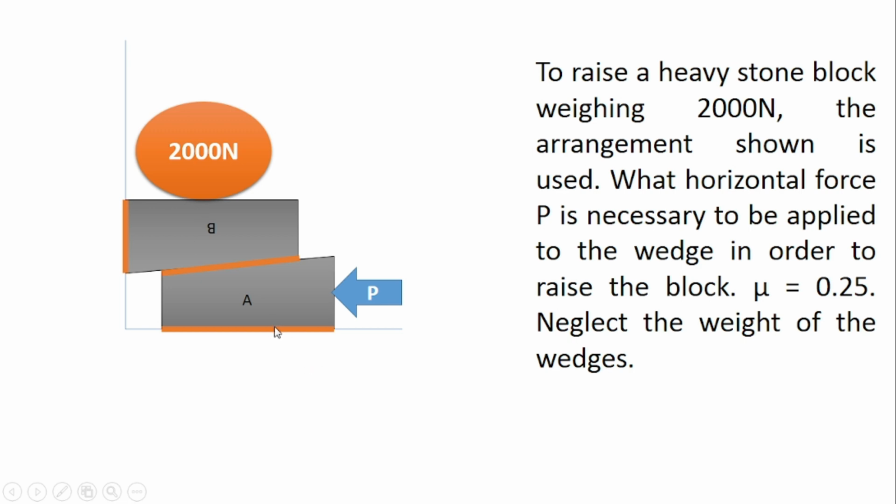So we have to draw the FBD for the 3 surfaces. While drawing the FBD, first start with drawing the blocks. Draw it at proper scale so that all the forces can be shown on that diagram and there should not be any confusion. So your figure should be neat and clean, so that will help to write the equation without any mistake. So this is my tip number 1.